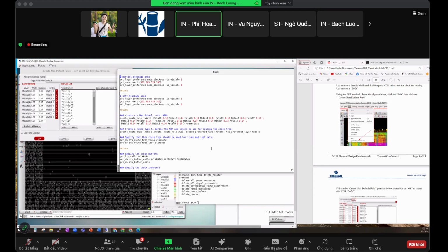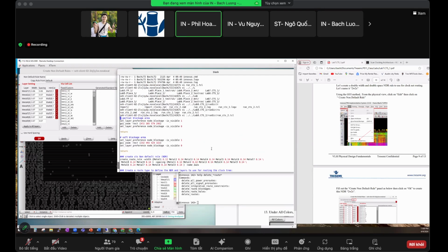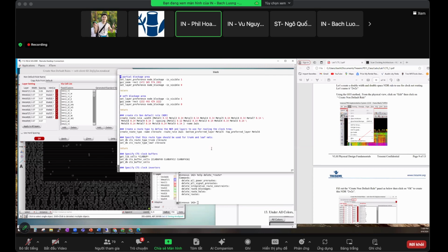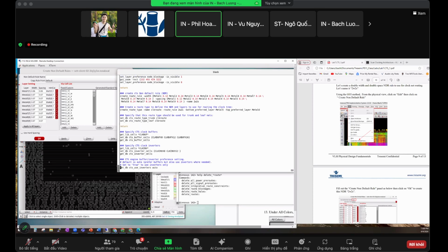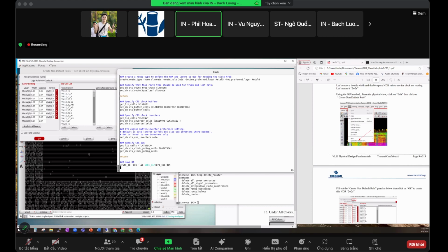Okay. So the integrated clock gating cells, typically you don't need to specify because they're attributes in the library that really have them defined, so the tool will look for them. In the lab, this is just showing you that if you don't have those attributes in the library, you can set them on the command line, but in practice, you don't need to do this.